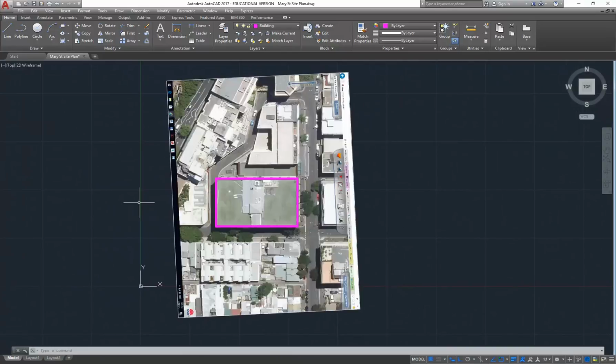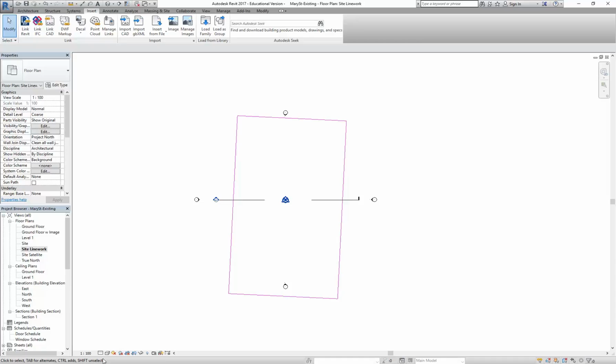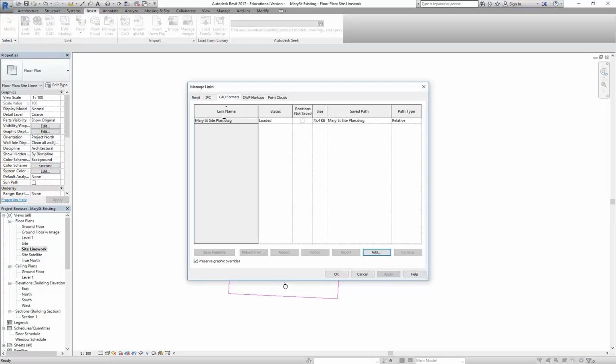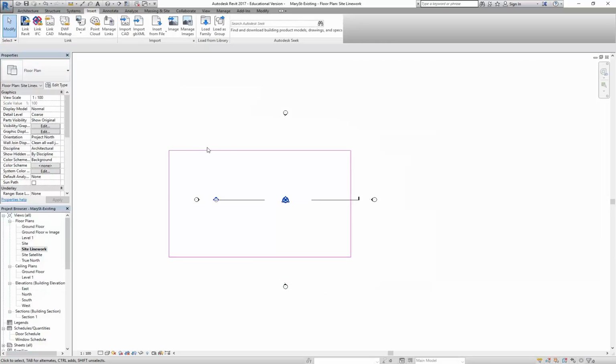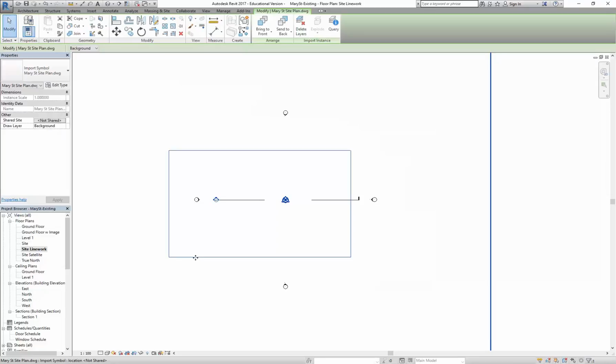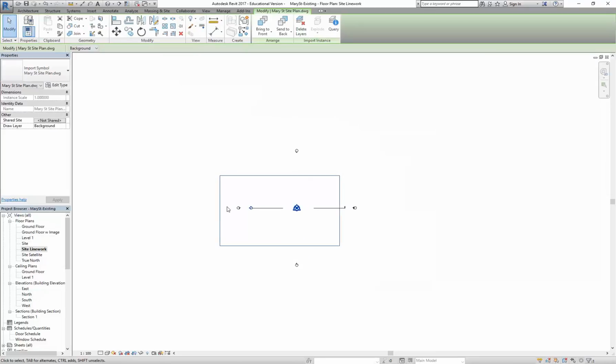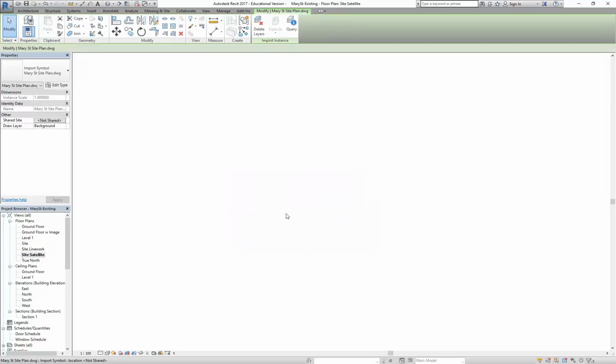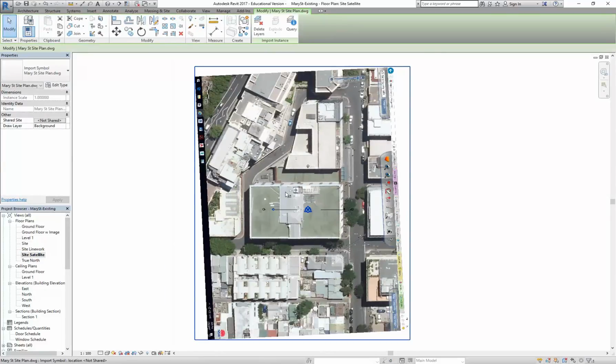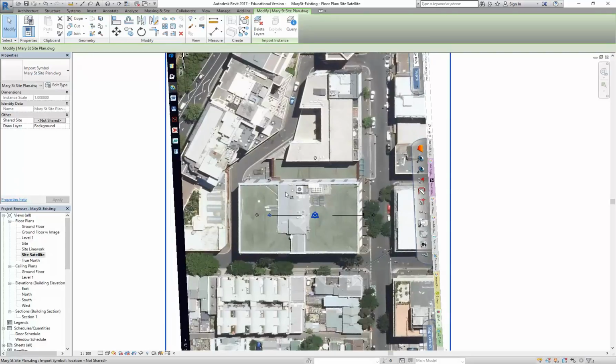Okay, so that's now ready to check back in AutoCAD, in Revit. So I'm going to save the file again. Back in Revit, again, insert, manage links, CAD formats, select file, reload, okay, and we can see then that the building, or the footprint, is rotated. Going back to site satellite, of course, that's been rotated along with it. But then, how do we line that up with the floor plan that we already have?